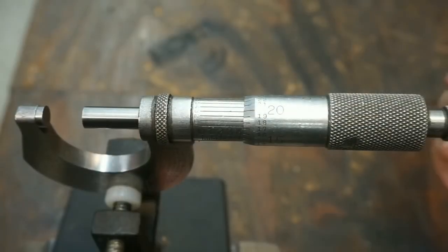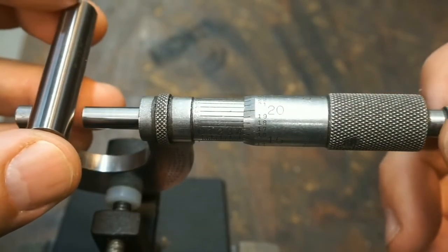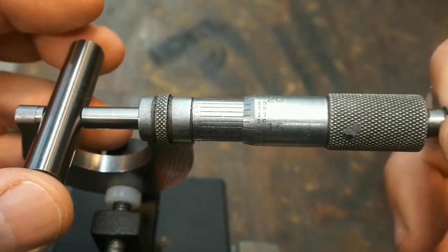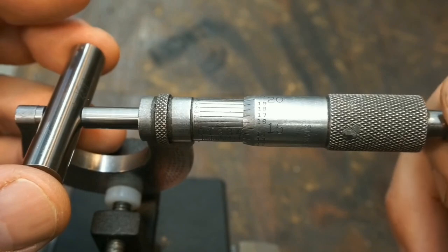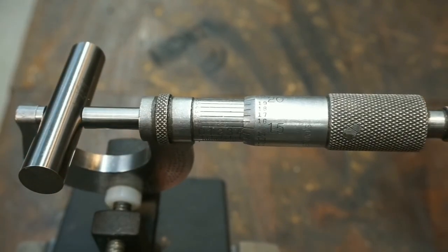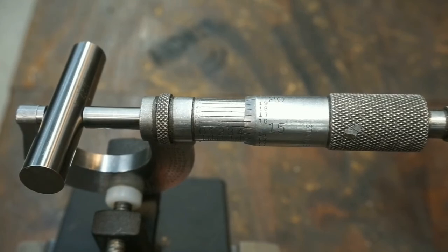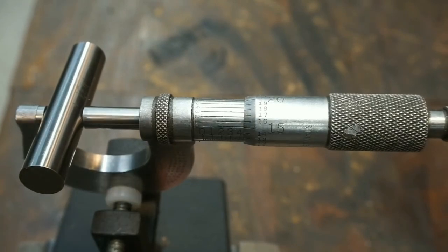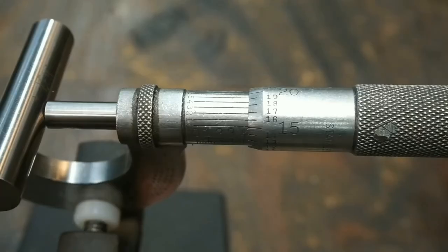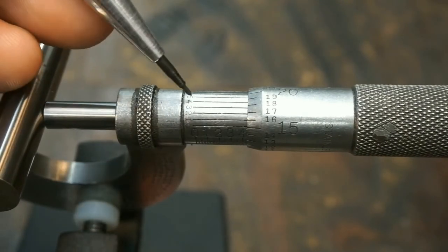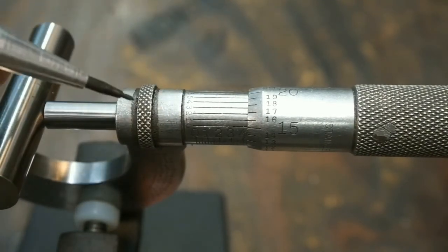All right, I'm going to demonstrate the tenth reading on the top of the mic now. We'll go ahead and put our 437 back in here and clamp it back in. So we already know we have a 437 thousandths reading, but our 0 is just slightly past. But if you'll notice on the top of the mic right there, on the top of that barrel, there we go. You see you have a series of parallel lines starting with